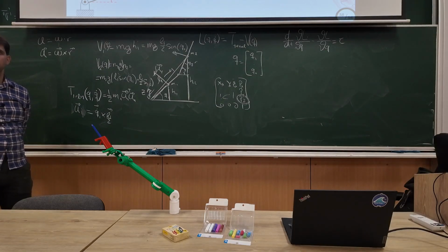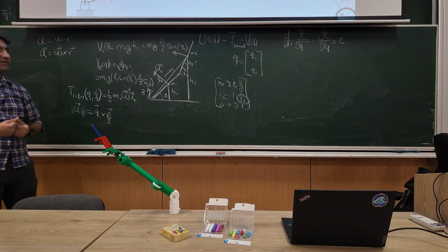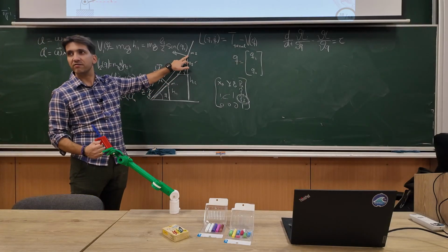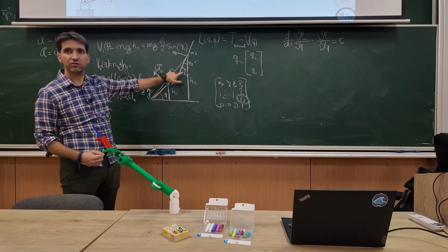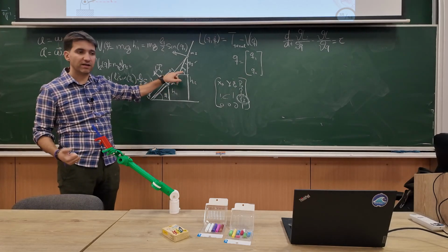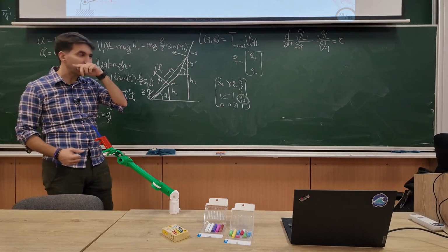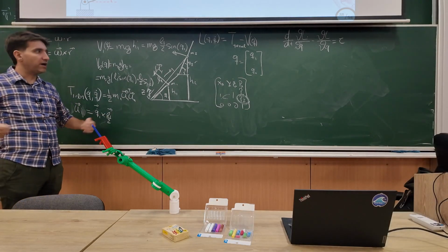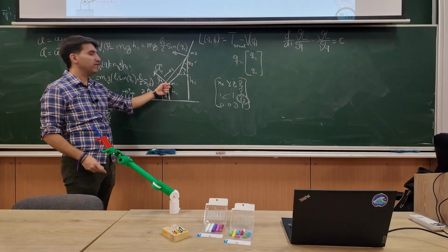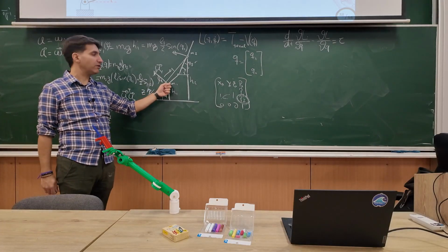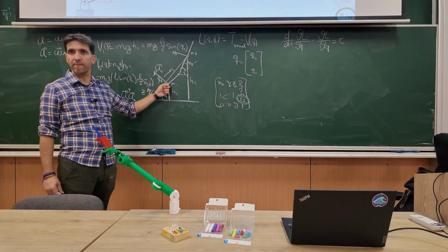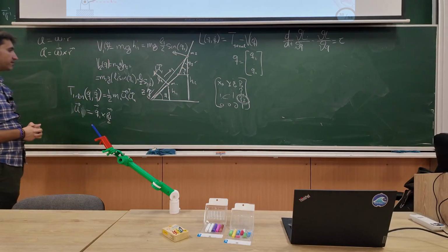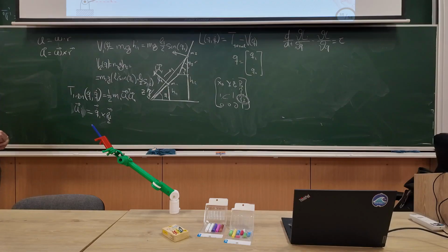The Jacobian, right? So what I'm trying to do is calculate the linear velocity of these masses as a function of the joint velocities, right? This is exactly what we did with the Jacobian. We did it for the end effector, but we can say that the end effector is here. I then calculate the Jacobian until mass 1, calculate the Jacobian until mass 2, right? This is stuff we know and we can use.